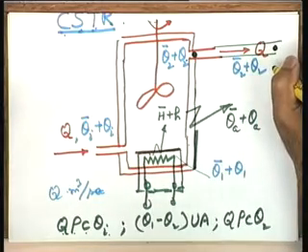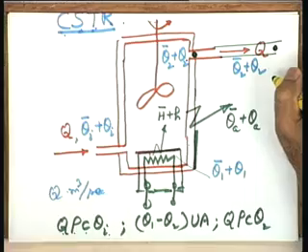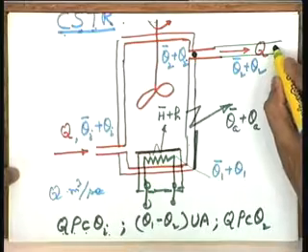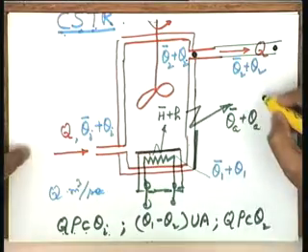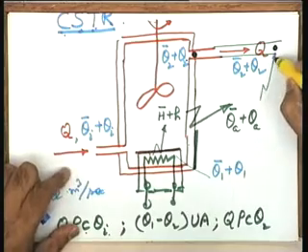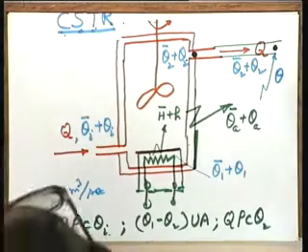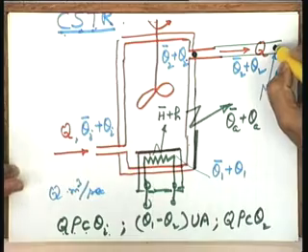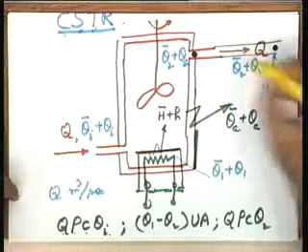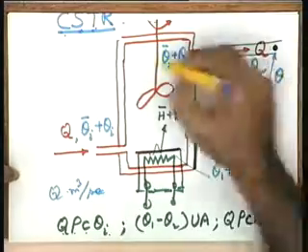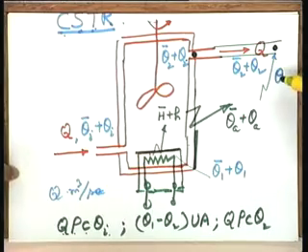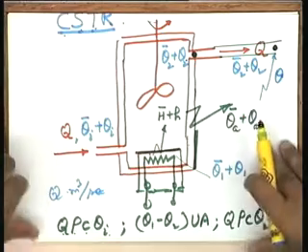So it means in this particular case, for the purpose of control system design, if you are setting up a control system model, a plant model, the output variable should be this temperature and not this temperature. Let me say that this temperature is theta only, let me use this variable for this, this temperature is theta. So a little change in your model, but a very important change. You have to now tell me what is the relationship between theta and theta 2, and using that relationship I will modify my earlier model and get the overall system model.